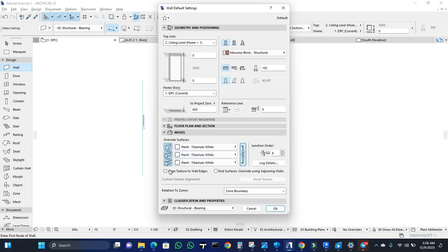Now also don't forget to check this box, because it's going to affect you while drawing. If you don't check this box, when 2 surfaces collide, when 2 walls join, let's use that word, the back, the other side, or should I say the adjacent of those intersections, is going to be a different material if you don't link both of them here.